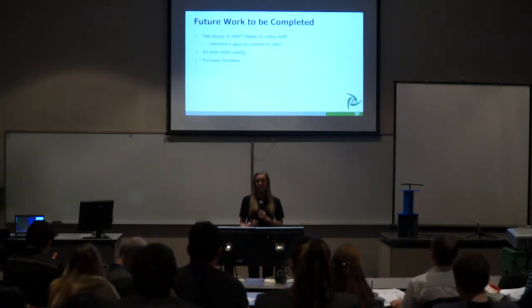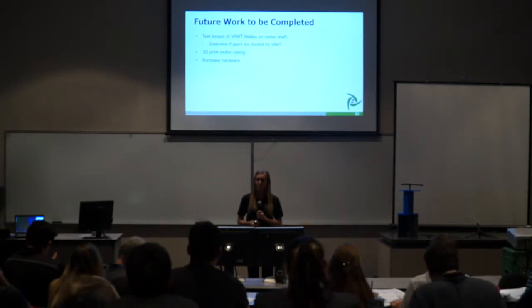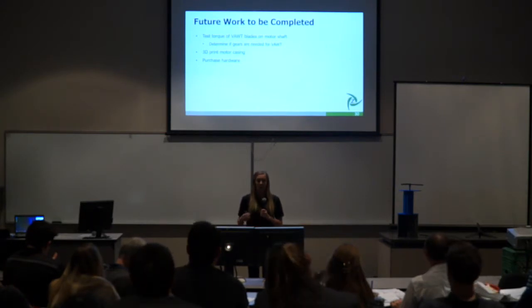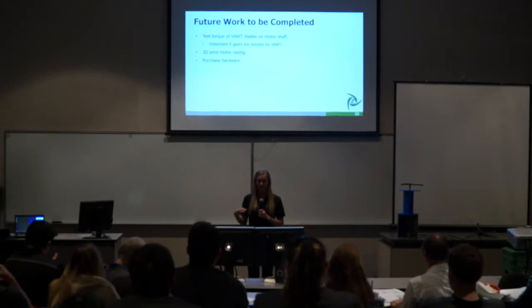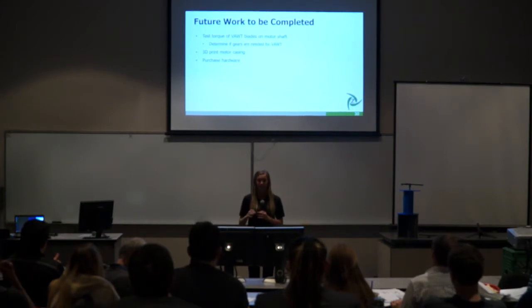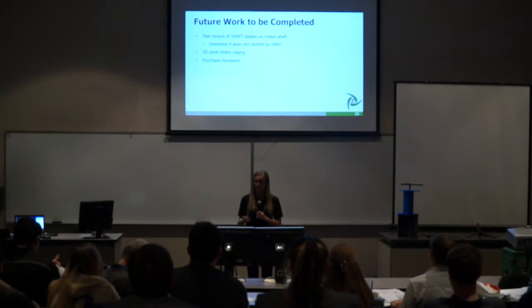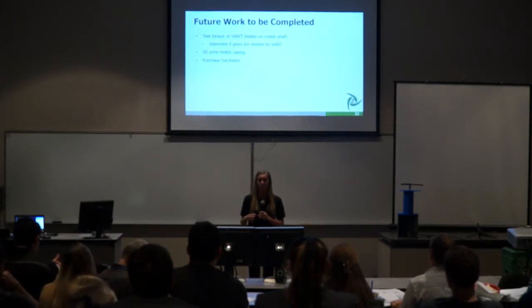The next steps for Project Zephyr to complete next semester regarding the mechanical design is to test the VAWT blades that have been test printed already, connected straight to the motor in 17-mile-per-hour wind speeds. These tests will determine if the VAWT design is creating a large enough torque to rotate the motor on its own, or if Project Zephyr will need to incorporate a gear design for the VAWT blades.